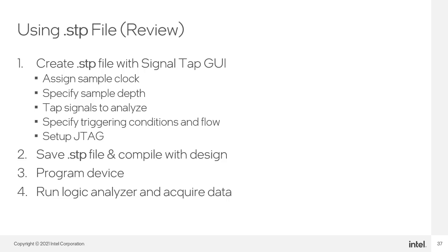Compile the project and program your target FPGA device. Finally, in the Signal Tap file window, run the logic analyzer instance or instances and analyze the acquired data. Subsequent parts of this training will go into more detail and highlight some additional features of the tool.